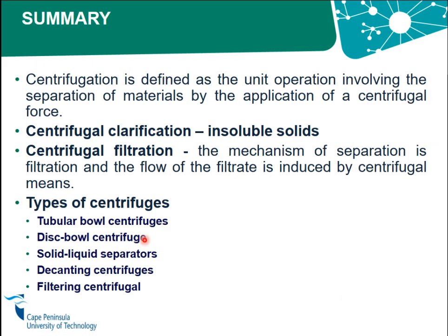So in summary, centrifugation is defined as the unit operation involving separation of materials by the application of centrifugal force. If we want to use centrifugal clarification, it's when we have insoluble solids that we want to remove from a liquid. With centrifugal filtration, the mechanism of separation is filtration, and the flow of the filtrate is induced by centrifugal means.